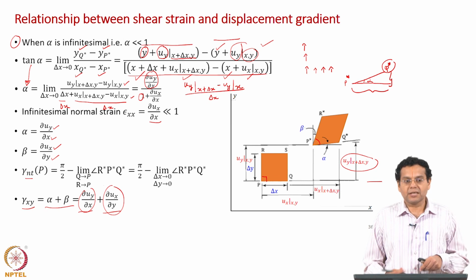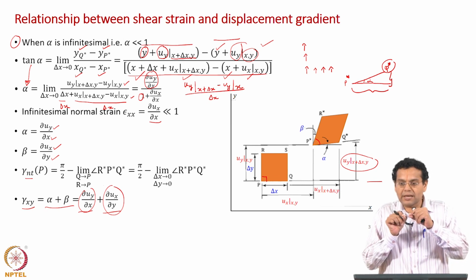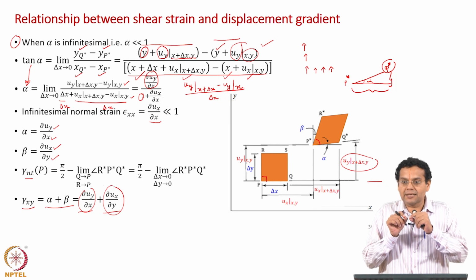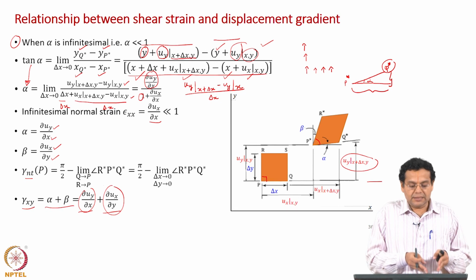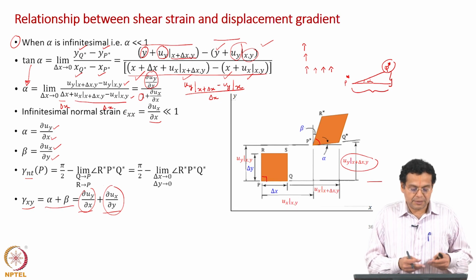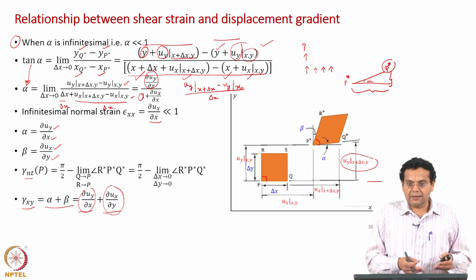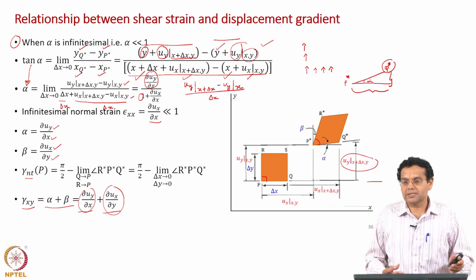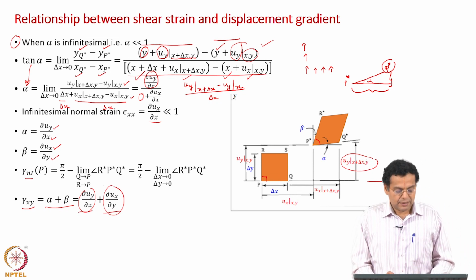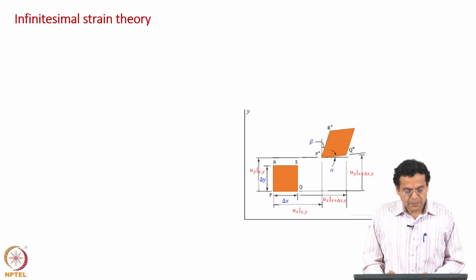What is the physical significance? At a point imagine 2 small lines, and what is the change in angle from initial state to final state, that is what you obtain by summing these 2 derivatives. Look at them as derivatives, more mathematical, meaning change of uy with x, ux with y, but when you sum up you get the shear strain, a more physically meaningful quantity.